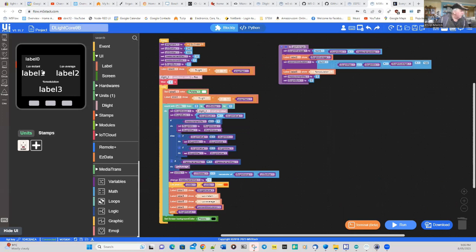You paint the labels. So I've got the program name going to come up here for label 0, and I'm identifying the measurements. So we've got the lux value for label 1. Label 2 is the average value. It's the average of 10 readings, and the percentage modulation is shown on the bottom. So here's the code, and it consists of a setup area, the loop on the bottom, and the average.